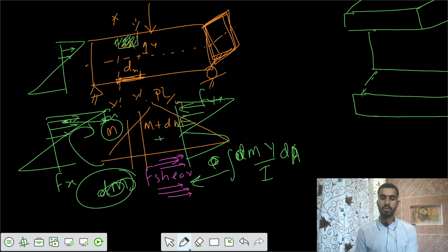That shear force equals tau times the thickness. There should be some shear stress acting on the bottom thickness, which equals b, and some length dx. So we said the area contributing to shear stress equals tau b dx. That was your shear force.